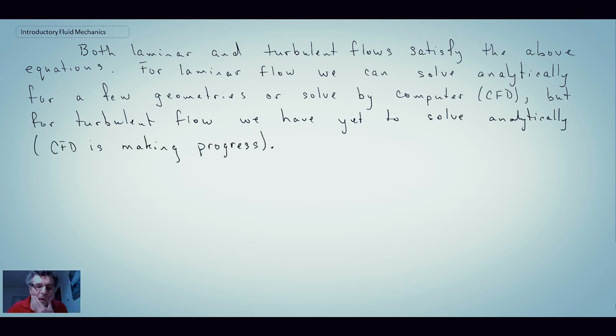Okay, so the thing about fluid mechanics is we have our governing equations, and we can have either a laminar flow or a turbulent flow, and they both satisfy the governing equations. And so in a way you could say that the equations are non-unique. You can have multiple solutions, and so we can have either the laminar or the turbulent state. Now the Reynolds number would change, but it's also related to instabilities that can develop in the flow as you go through the transition process.